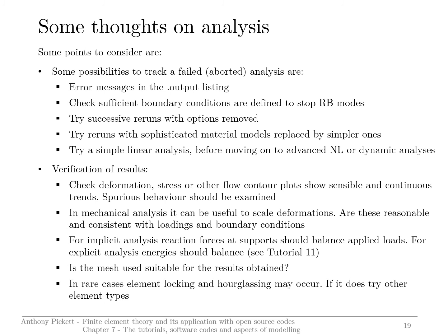It's always very useful to try and do a linear analysis before you move on and try a non-linear or dynamic analysis. Essentially, if the linear analysis doesn't produce sensible results, then you're not going to get a complicated non-linear or dynamic analysis to work.